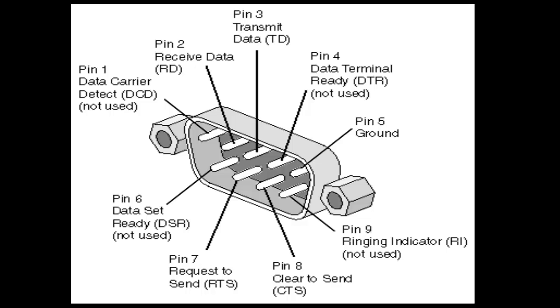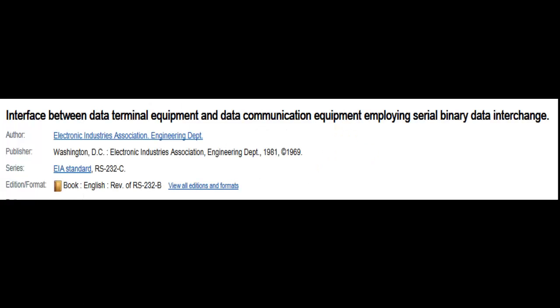When you look at a serial plug, you'll notice the pins inside the plug itself. Each of the pins has its own job when it comes to sending and receiving data. For example, on the standard 9-pin RS-232 connector, pin 3 is designated to transmit data, pin 2 is tasked with the job of receiving data, and pin 5 is the common ground. When you create a driver based on serial control, the Electronic Industries Association RS-232 standard is assumed.